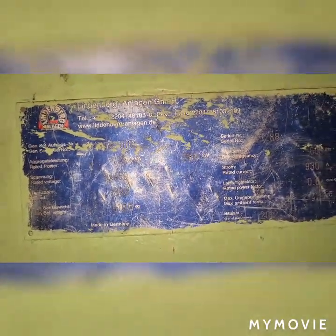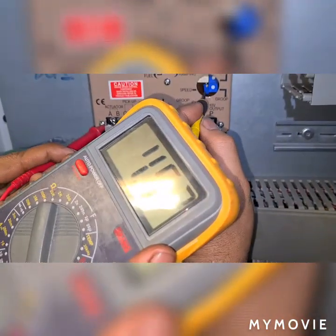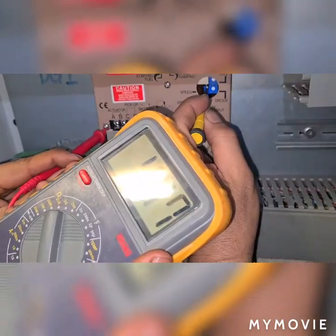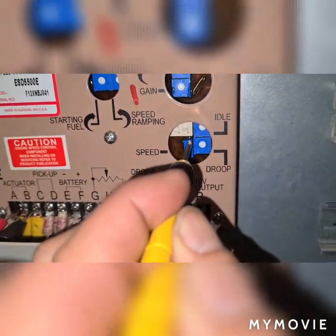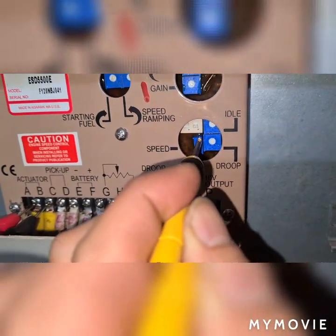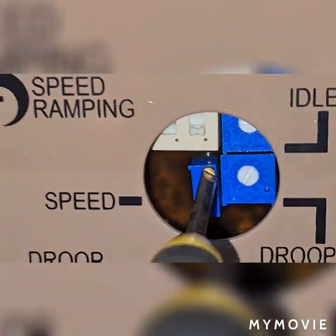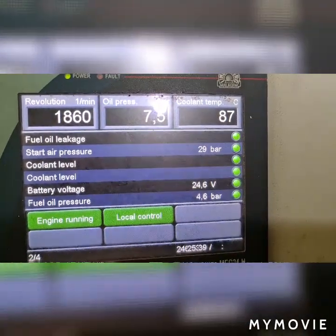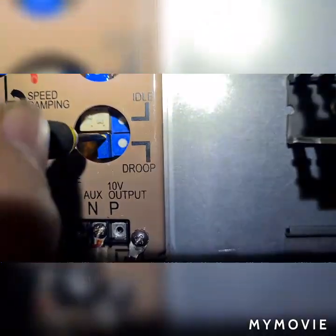We verify that the RPM value of our generator needs to be 1800 revolutions per minute while it is rotated in idle position, and we adjusted the speed potentiometer in a counterclockwise direction to reduce the speed, you see, and we measure the voltage across our actuator at 4.5 volts.